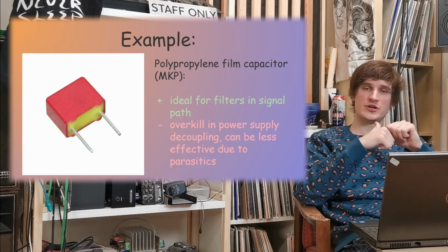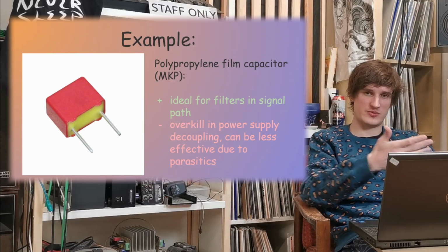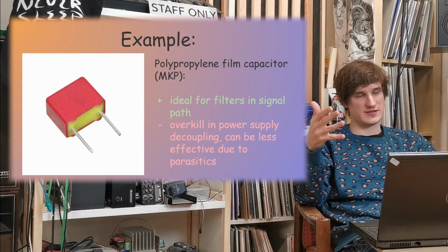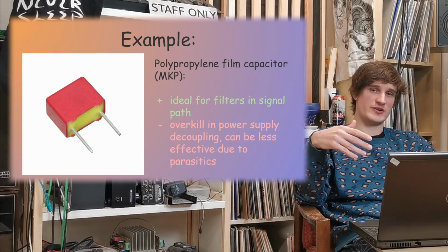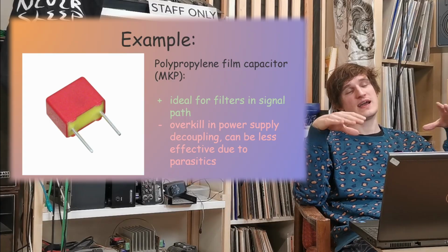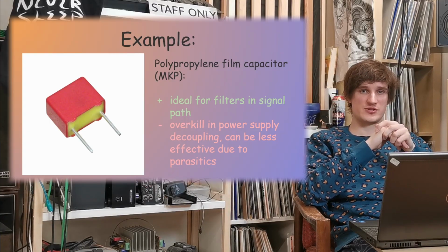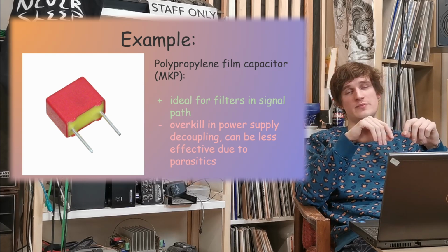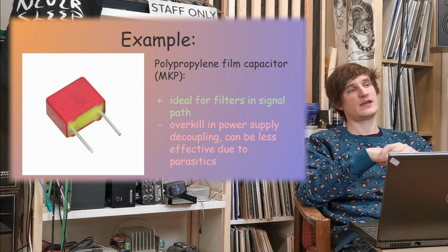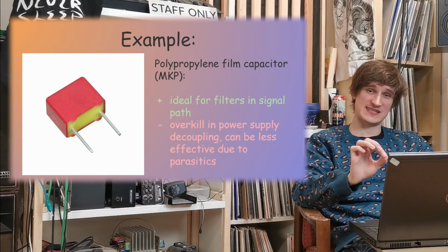First of all, you don't need the parameters that polypropylene film capacitors bring in the application of decoupling. You would rather choose just a ceramic capacitor in this application. And also, the other thing is that polypropylene film capacitors are still mainly available as THT elements, so through-hole components, and this also introduces some parasitics.